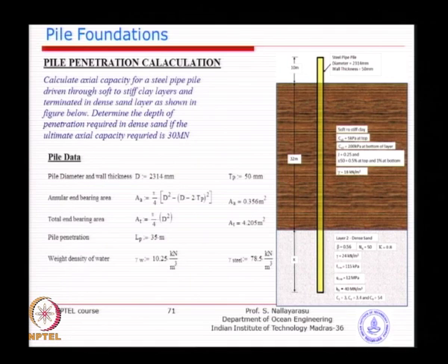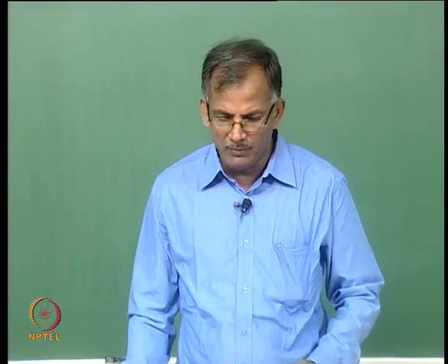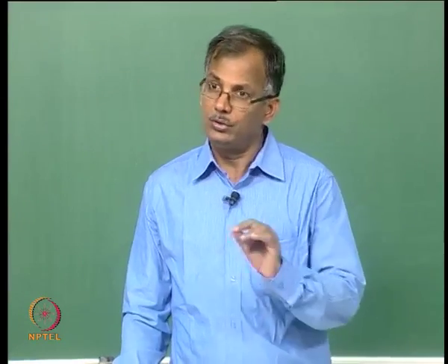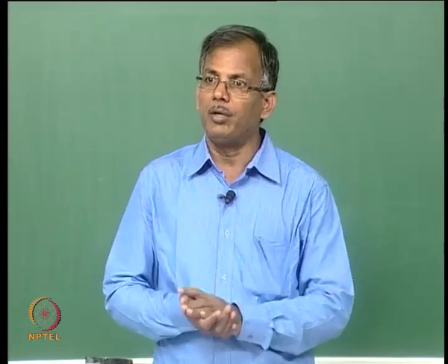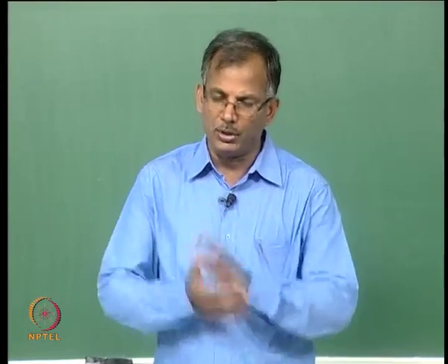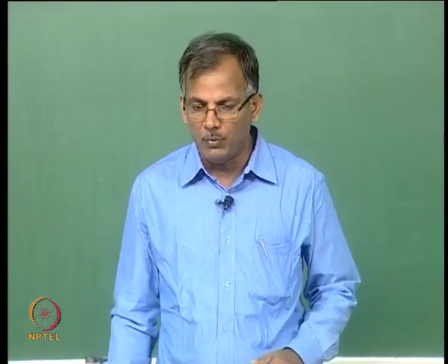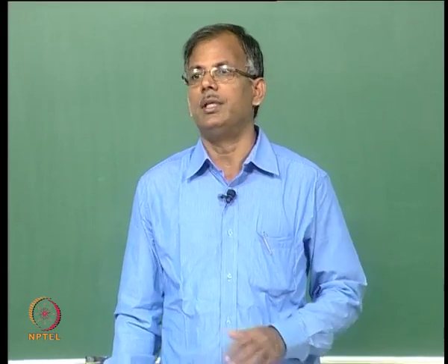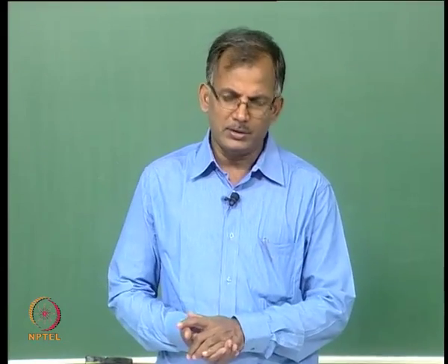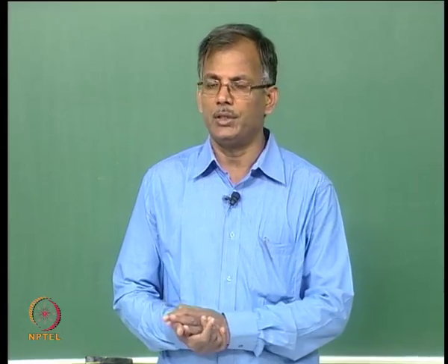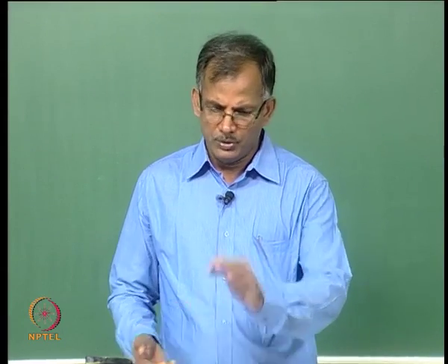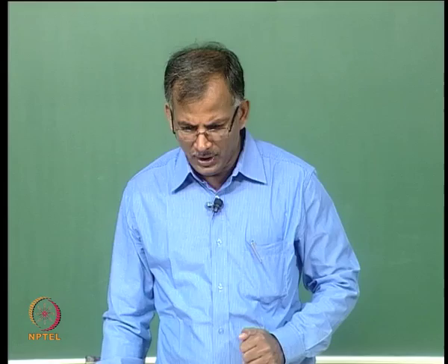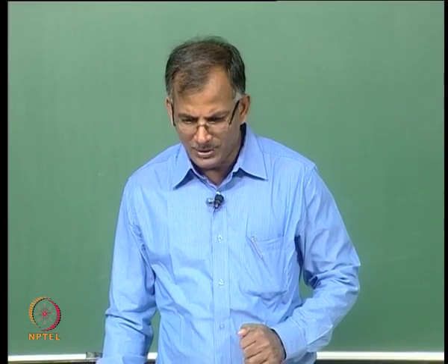Which we discussed in the various cases, 3 cases we saw. So, in this case, whether we want to go for 3 diameters just to achieve end bearing, or go further down to take into account some more skin friction, all depends on what strength is available from this layer. So, this is a very interesting problem which you will face in real life. The idea is, you see here the second layer is a sandy layer.